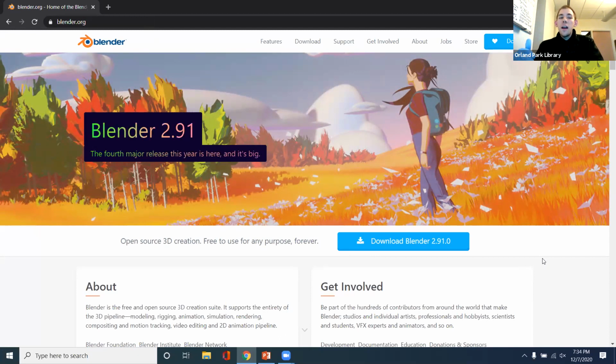mixing two colors, no, because sometimes if you try to unload a filament, you have to load in another one and then have the thing cool down. So as it's starting, there's not really an option for it to stop and mix two colors, because if you're using something that's dissolvable and then something that's not, it doesn't mix well as it's being printed. So that's a factor you need to consider for what kind of thing you're making.